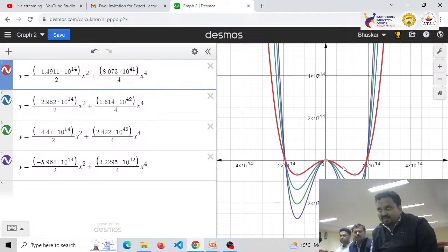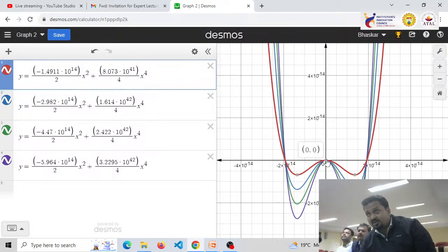But the negative capacitance state in a ferroelectric capacitor is highly unstable. If you make a capacitor out of a ferroelectric material and analyze it using an impedance analyzer, it will show a positive value. Why is this happening? Because this transient negative capacitance state in ferroelectric is highly unstable. If you try to put charge on this slope, it automatically falls into one of the minima. That's why when you put your ferroelectric capacitor in an impedance analyzer, you are not able to see negative capacitance but a positive capacitance.